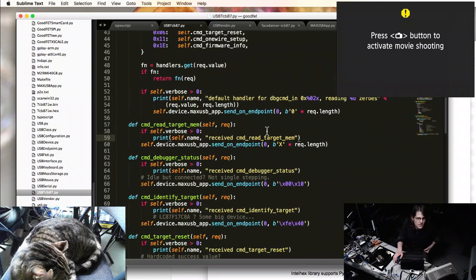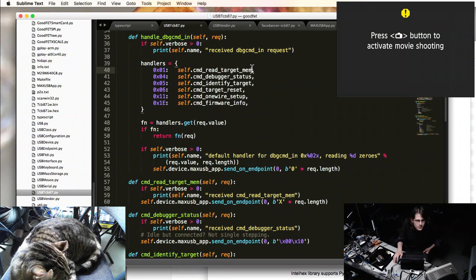I should be more specific about what kind of memory this is, because there are many kinds of memory. This is target program memory, which is usually flash, but these microcontrollers also come in a ROM version. And the documentation is written as if the ROM version is like the normal version, so I hesitate to even call flash normal in this chip.